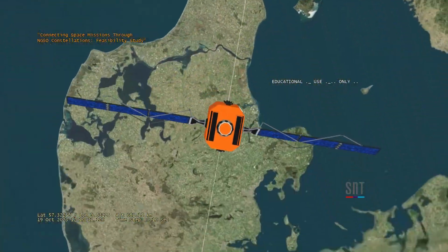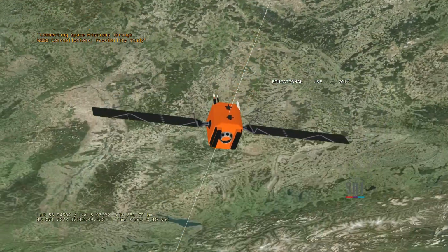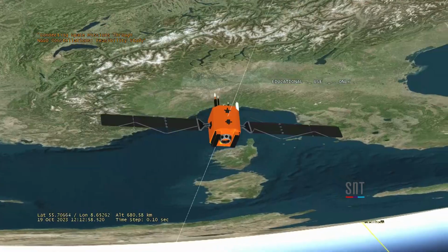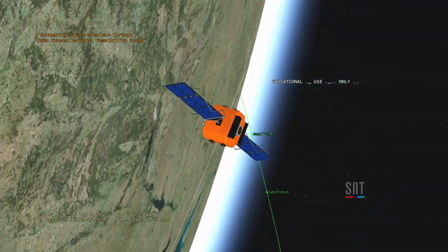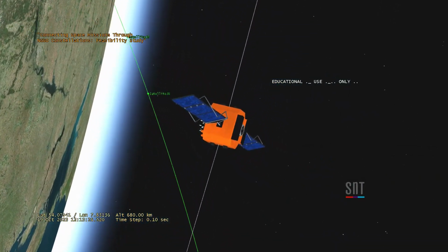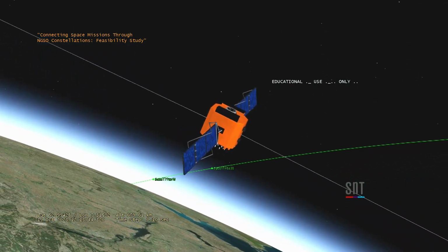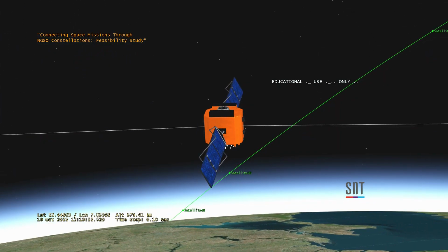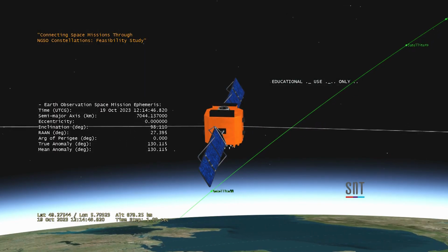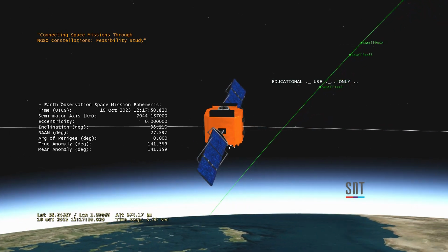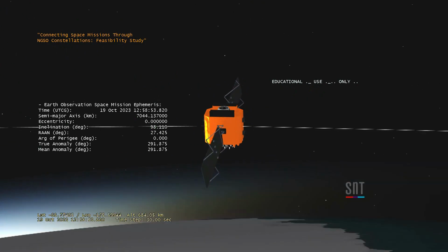A space mission on duty, like an Earth observation satellite gathering data at around 660-kilometer altitude, normally offloads the acquired data through a geo-intersatellite data relay system and its polar gateways upon revisit, meaning non-real-time tasking. However, if we configure the space mission with a commercial off-the-shelf ground terminal that can connect to already existing satellite internet providers in medium and low Earth orbit like O3b, OneWeb, and Starlink, it can not only offload on demand and in real time, but also reduce the mission's costs.